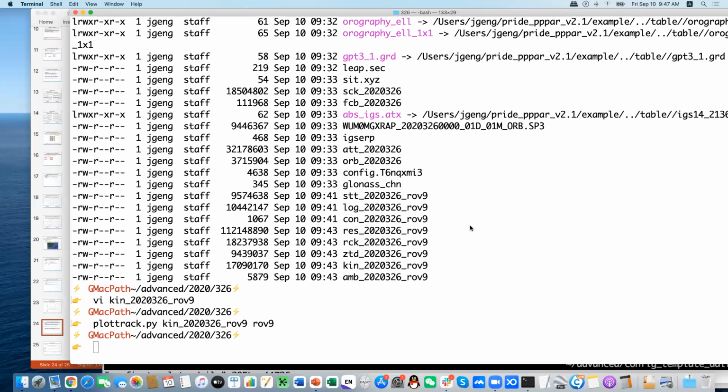Are BeiDou GEO satellites used for AR, or are they used for float solution only? For the GEO satellites, they are used only for float solution. They're not used for ambiguity fixing, because the GEO satellites don't have precise orbits or clocks, and that will affect their ambiguity fixing rates. So we just exclude them from our ambiguity fixing process. Their weights in the data processing are decreased by 9 times, as I have mentioned in the satellite list. You can see the numbers I put behind them.